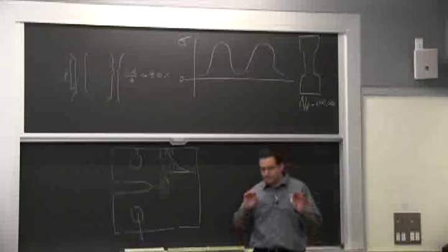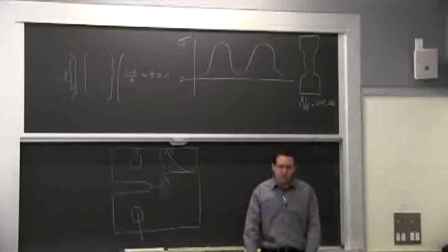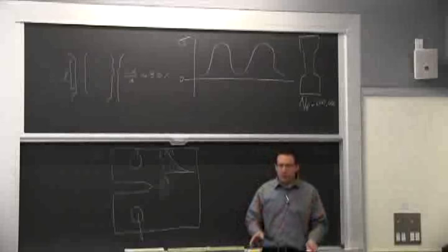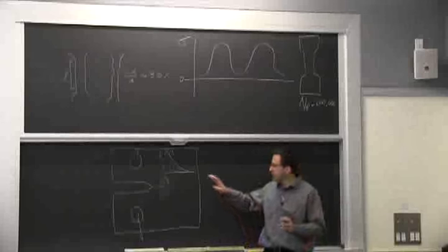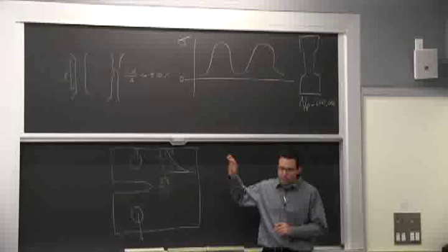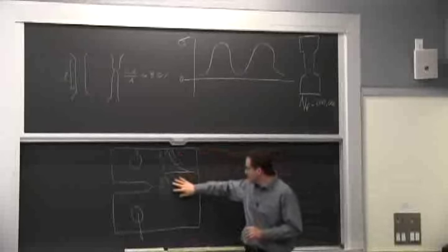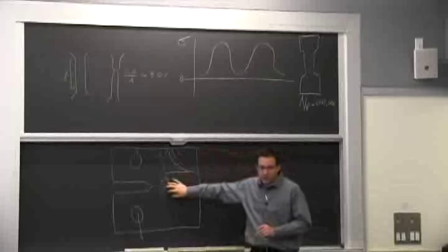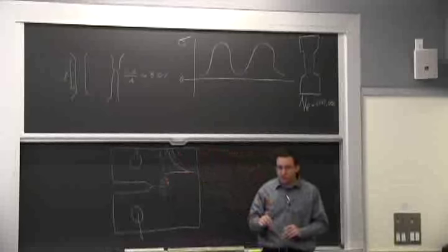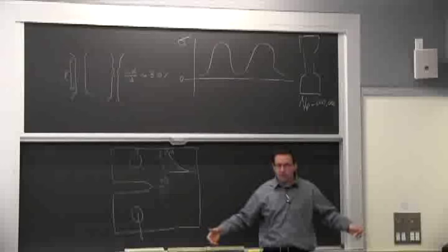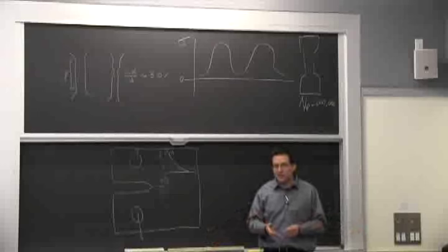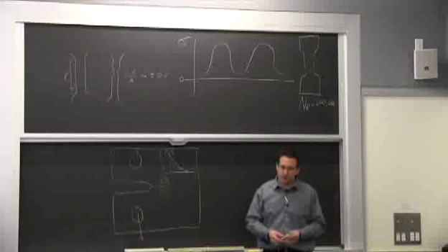So I just thought that was about the right level to warn everybody that there is a limitation here, and that's why we keep referring to linear elastic fracture mechanics, and we always need to have a small zone here. It is true when we have very big samples. Sometimes you have a thin sample of a very ductile material, and now you have to use other methods, and we'll cover that for sheets and other applications.